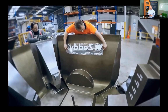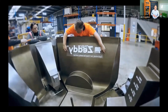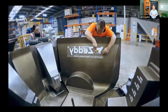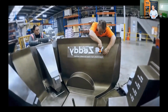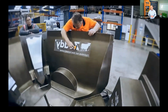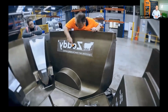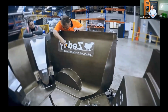You could say quite a tricky graphic to apply if you hadn't had any training at all. But these guys, all they've done is trained with those little small graphics. So here he's aligning the graphic onto the mold, then using the rubber-faced roller, he's working from the center of the graphic outwards just to avoid trapping any air bubbles. You can see him moving across the letters just to expel all the air and make sure it has good adhesion with the mold.